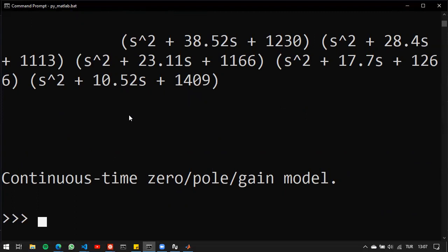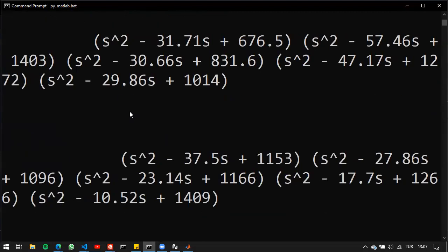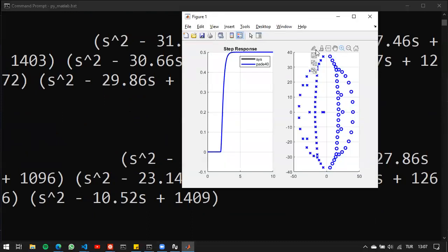This is a 42nd order transfer function, with 40 zeros, of course. That brings us to the following. If we want to design a controller and have a good approximation, we should use a higher order. But the limitation here is that too many poles and zeros will also prevent us from designing a controller, because we want to try to have a certain dominance in order to have good behavior.